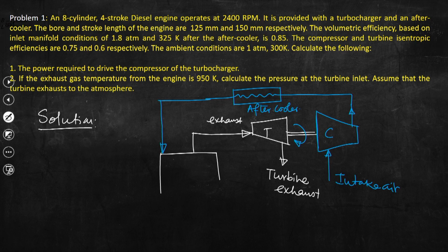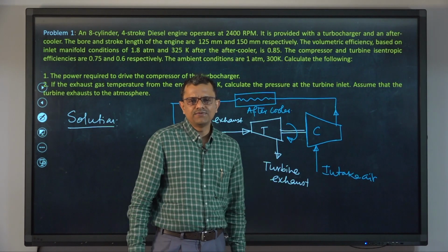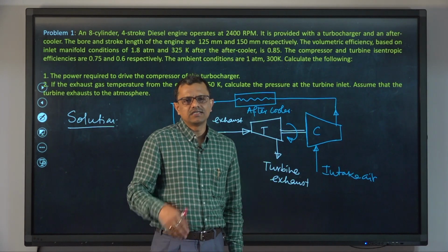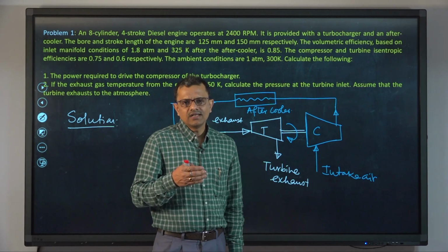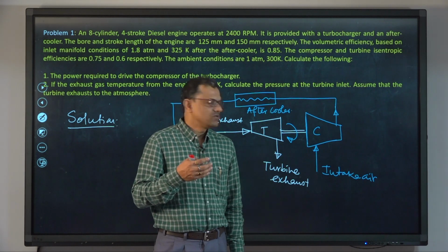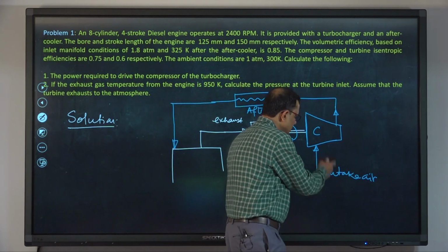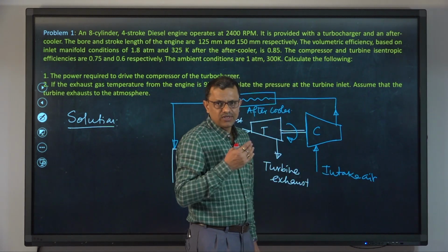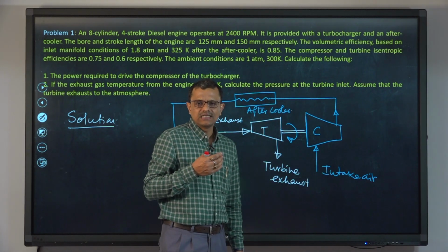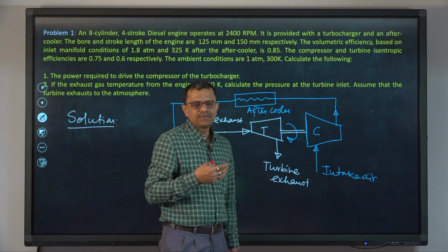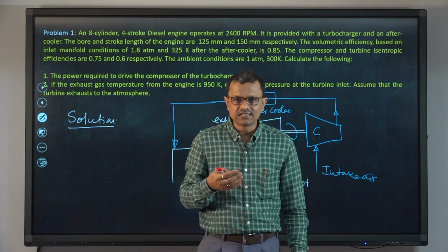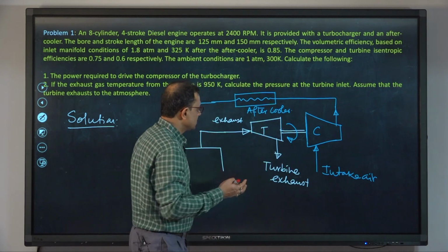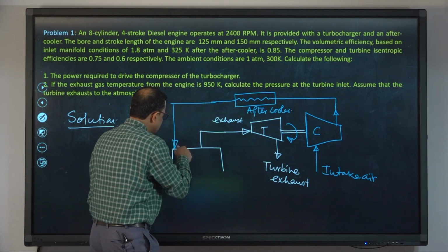This after cooler is provided, if you can recall the discussion we had in our last class, when the compressor is compressing the intake air, temperature also will increase. If temperature increases, the rise in temperature will increase subsequently in the engine itself, right, because this air will be taken during the intake stroke to the engine.